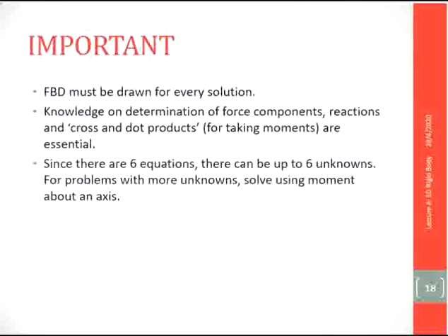Okay, that's all for the list of the reactions at the supports. What you need to remember for every rigid body problem is that you need to draw the free body diagram and know every force component and reaction, and also know that for the moments you use the cross and dot product.